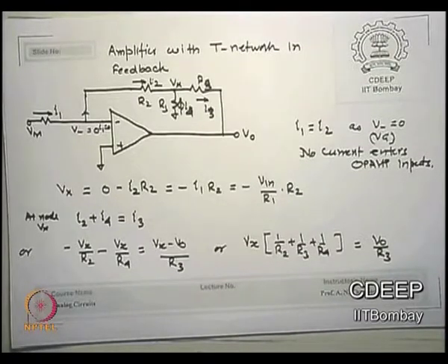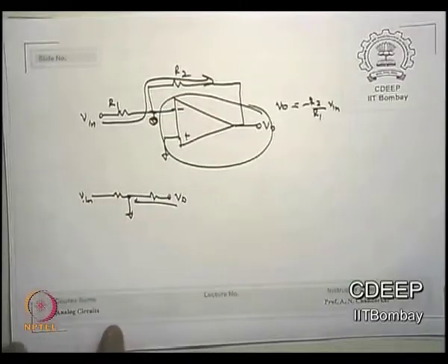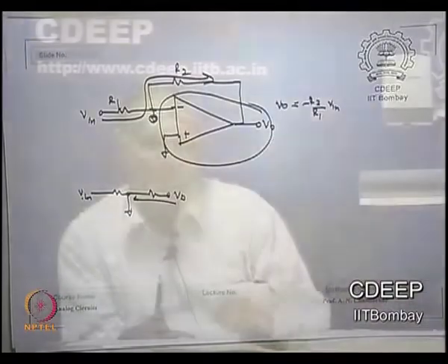Okay, here is R2, which I am showing again and again here. From here, can you tell me, if I want to increase the gain, or rather output voltage, what should I increase? R2. Either I should make R1 very small or make R2 very large, okay. So larger the R2, larger is the gain, I know very well now from there.